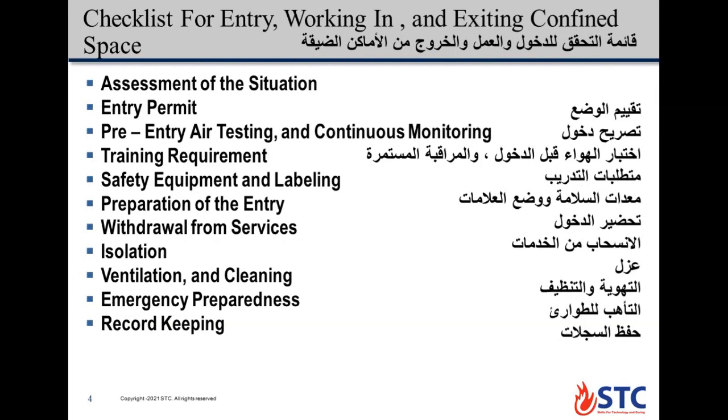Again: assessment of the situation, entry permit, pre-entry air testing and condition monitoring, training required, safety equipment and labeling, preparation of the entry, withdrawal from surface, isolation, ventilation and cleaning, emergency preparedness, and record keeping.